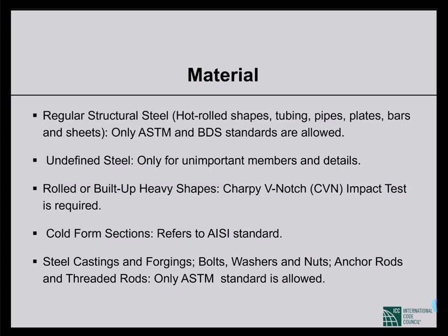But in Bangladesh, if we want to design steel structure, we must follow material standards ASTM and BDS. So what is the choice? The choice is, wherever the place we import the steel sections from, those sections must pass through all the tests mentioned in the ASTM.